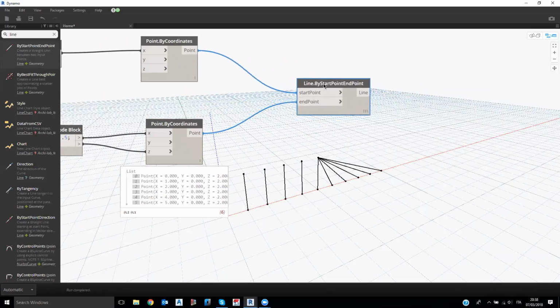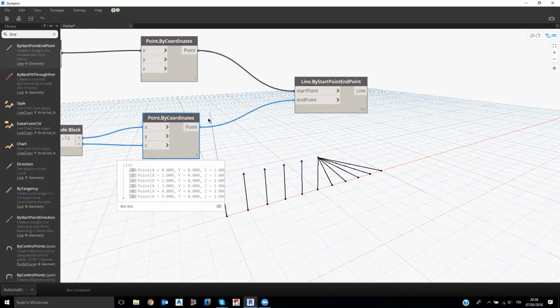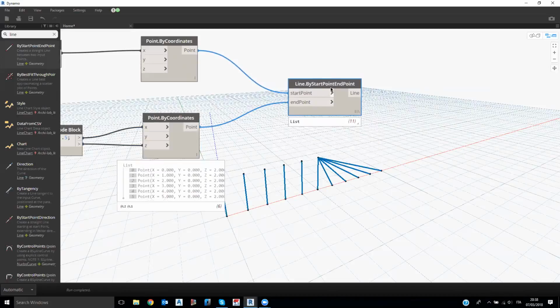So this is a very important point in Dynamo, and we will use this many times, and sometimes the result of your workflow can change dramatically if you change the type of lacing. So be careful, because sometimes you will need to change it from shortest into longest. Let's say that probably 70% of the times you will use the shortest connection because you have more or less always the same amount of information that you want to connect. Probably 20% of the times you will need the longest one to be used. And let's say just 10% or 5% of the times you will need the cross product. So it's very unlikely used, but sometimes you need to use it.